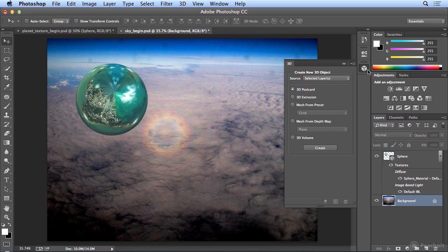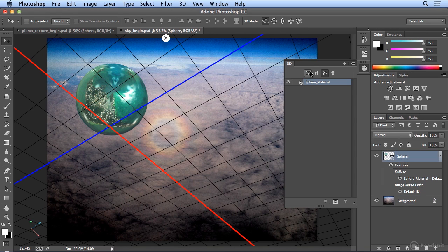So if I go back to my 3D panel and select my 3D object and go back to Environment, the whole scene, at the bottom, you'll see Render. And now in Photoshop CC, the Ray Trace progress bar actually shows more detail. Both time and percentage are shown. So I am ready to commit to this. I will click Render.